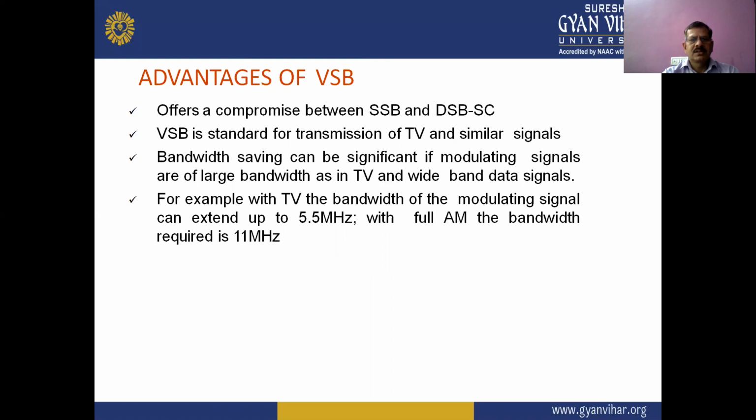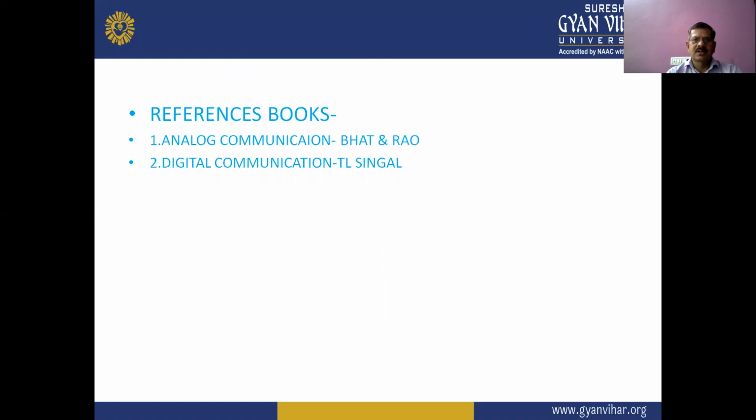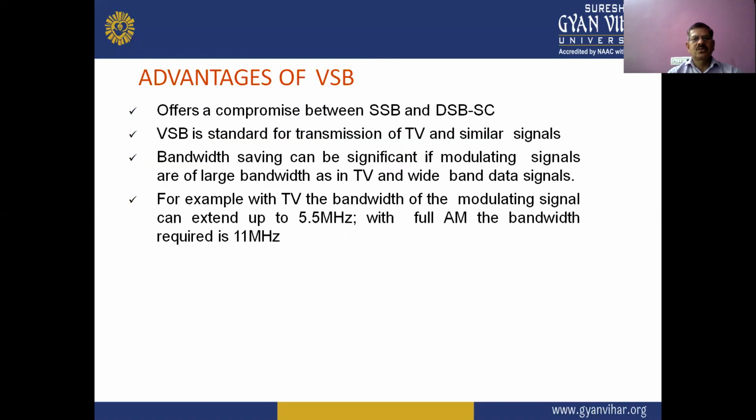For example, with TV, the bandwidth of the modulation signal can extend up to 5.5 megahertz. With full AM, the bandwidth required is 11 megahertz. So these are some advantages of the VSB signals.